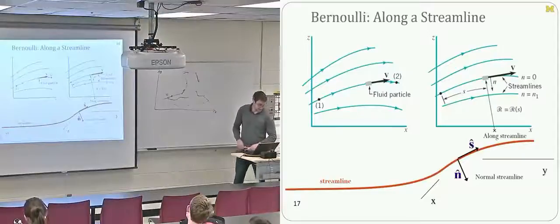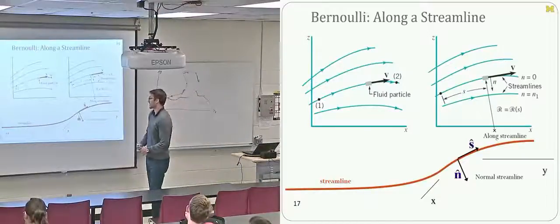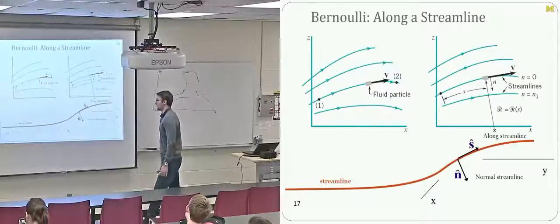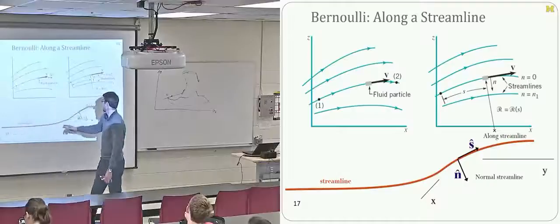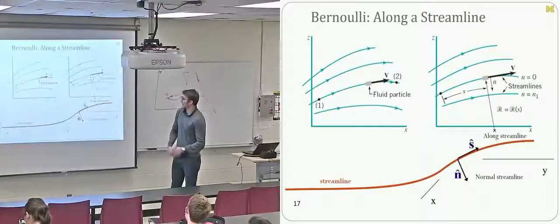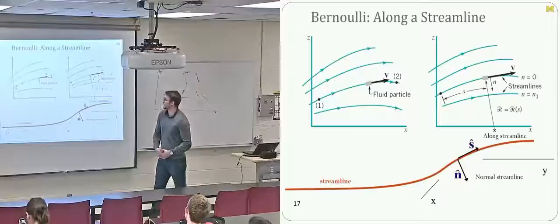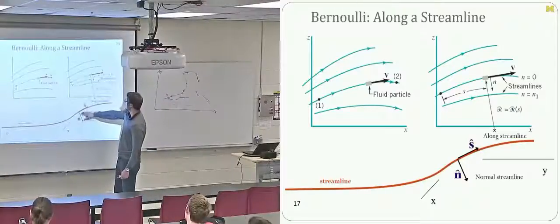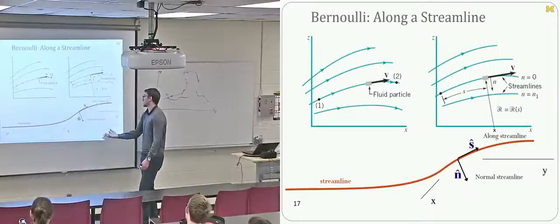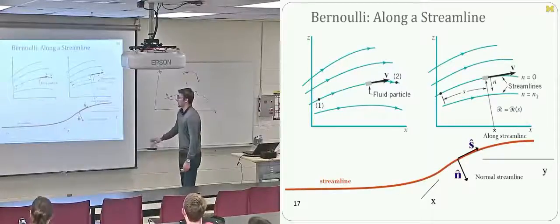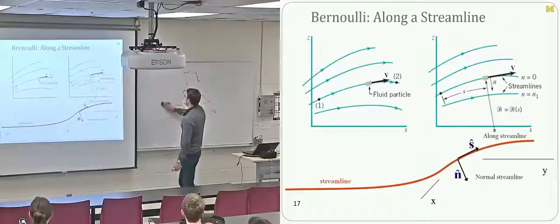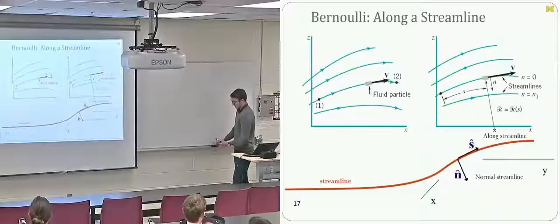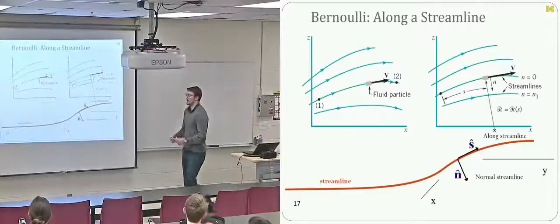So this is how we're going to start talking about motion of particles along these streamlines. We saw in that last video that fluid particles entering over here tend to ride the streamline like it's a rail. We tend to describe the streamline, or describe forces and such on the streamline, in these streamwise fixed coordinates. But how do we actually describe motion along the streamline itself? This is when we start to talk about streamline kinematics.